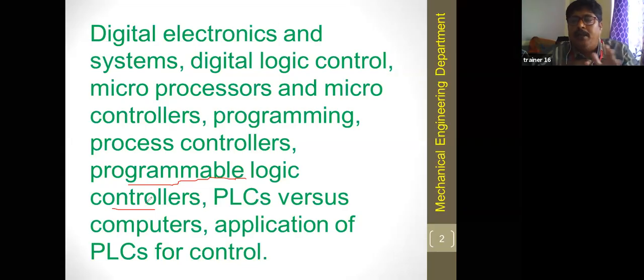So the tool name and then processes, and then you are giving codes, right? Part programming. You write the program in software, the NC part program, and then you feed it to the CNC machine. Once you write the program and feed it to the CNC machine, then without any human involvement all the operations are carried out on the job, and lastly we get our desired piece. Similarly here also.